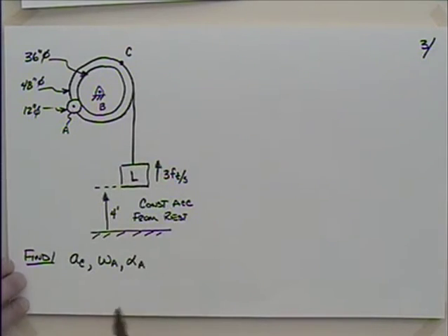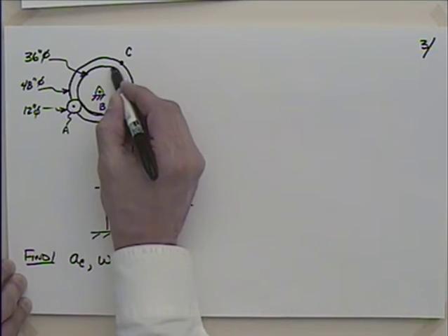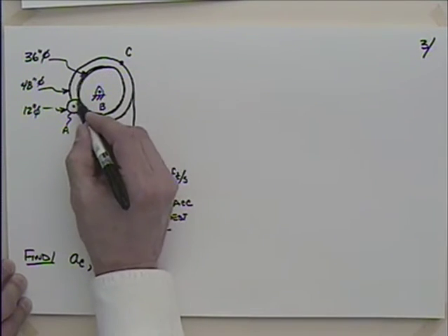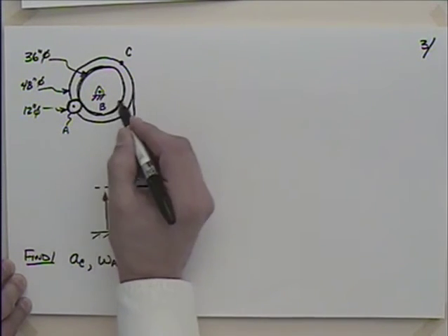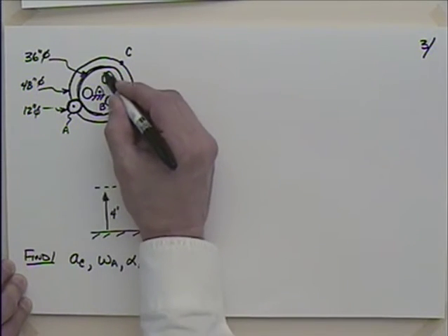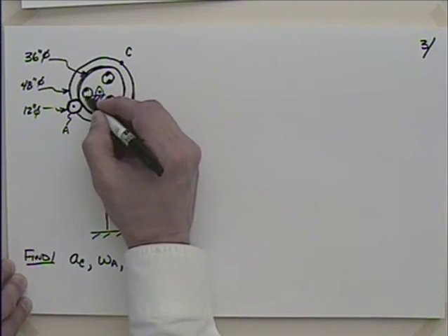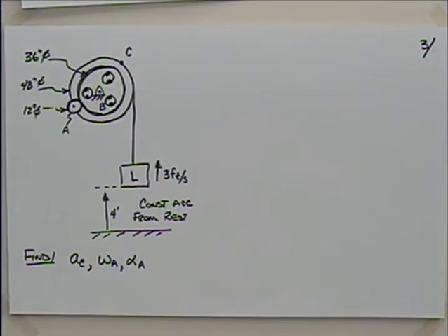this pinion gear A. So apparently there's this gear B here that's engaging with the pinion gear A, and gear B is apparently probably welded. Maybe they've got some big holes here and they have welded this larger gear B to the drum C that the cable's actually wrapping around. Okay, so they've made it like that.